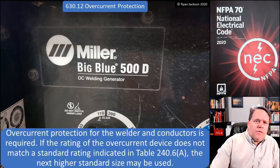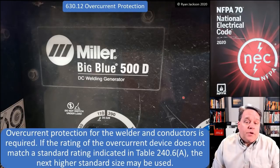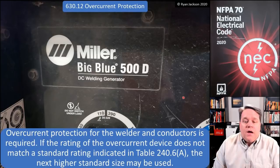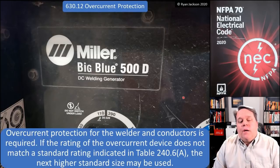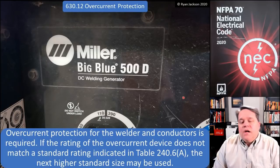When it comes to the overcurrent protection, 630.12 says that the overcurrent protection for the welder and the conductors is required. And if the rating of the overcurrent device does not match a standard rating indicated in table 240.6(A), the next higher standard size can be used. Now,